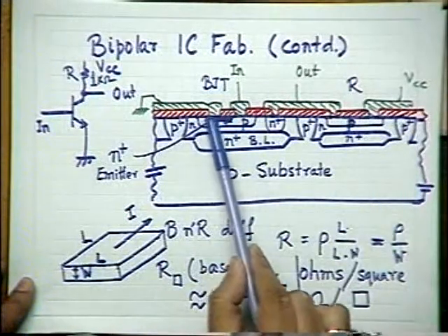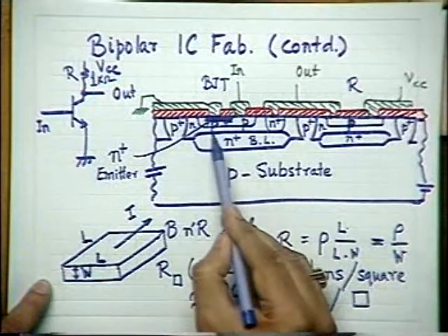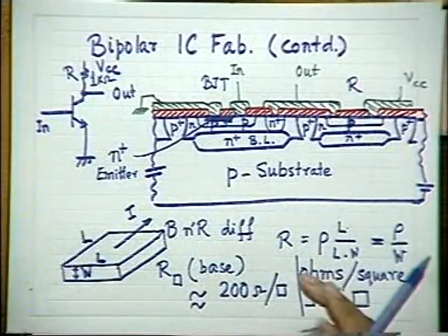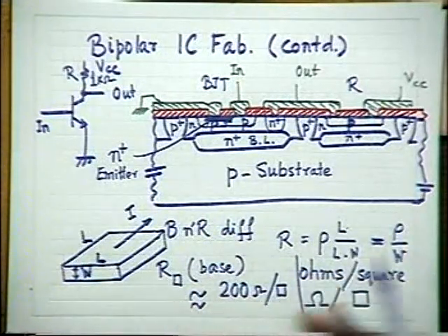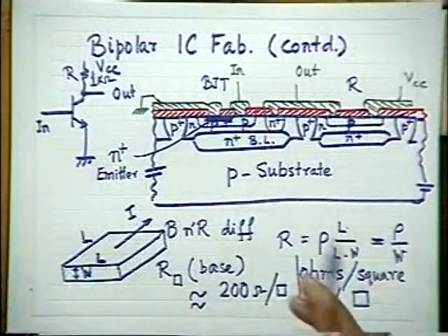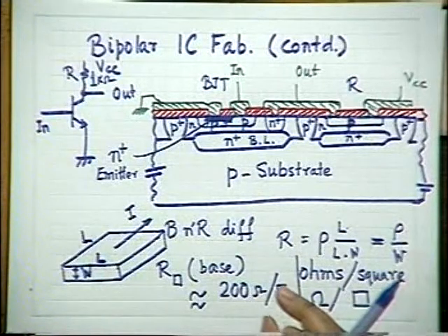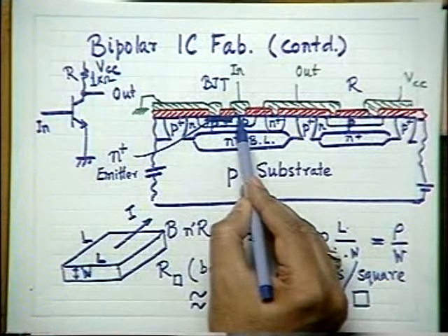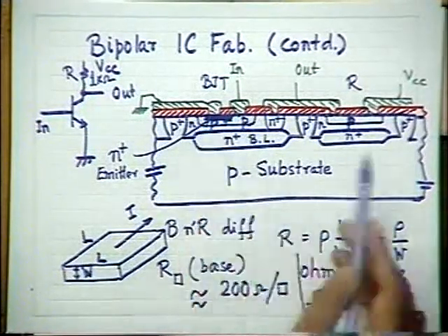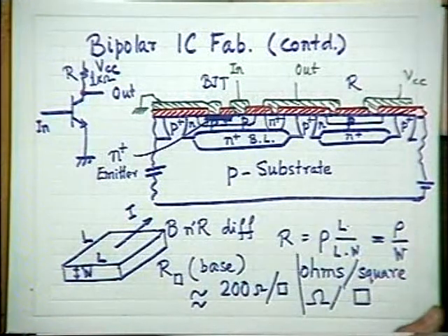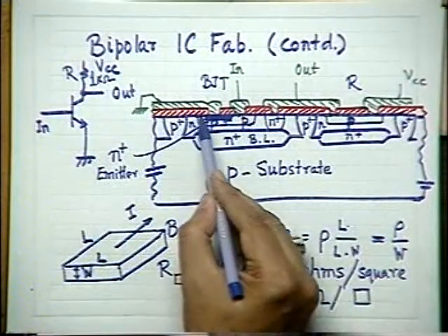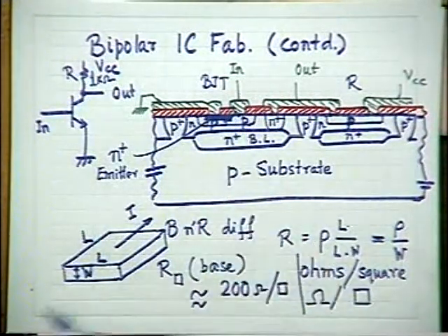Am I correct? Between this emitter layer and the collector, this base layer is very narrow, usually of the order of a micron. Otherwise, if you do not maintain that, your gain will be very less. In order to achieve a high transistor gain, the physical base width should be of the order of a micron. So if I have a contact here and here, on either side, suppose I don't use this structure as a transistor. In a separate block, I make similar things, and I put a contact here and a contact here. So what will happen?